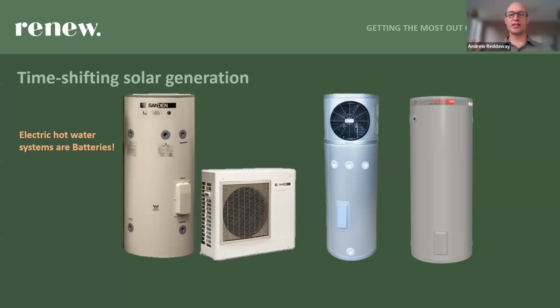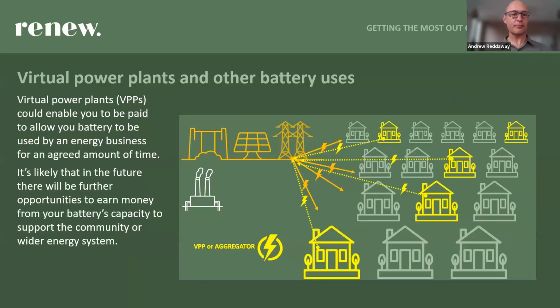The thing to watch out for is if you have a really cloudy day, then even if you've got it on a timer running around the middle of the day, your solar may not be covering it all. So you may still be importing grid electricity to heat up a portion of that energy to heat your water. And there are ways around that, but we may not have time to cover them in this presentation. We have other webinars to talk about all that type of stuff.